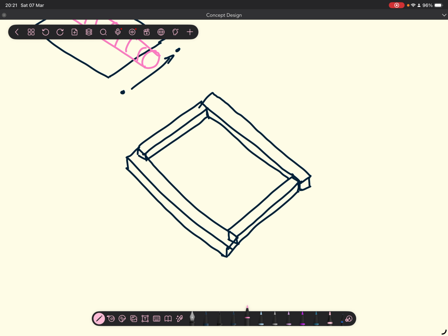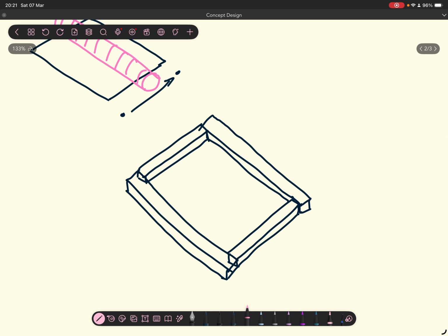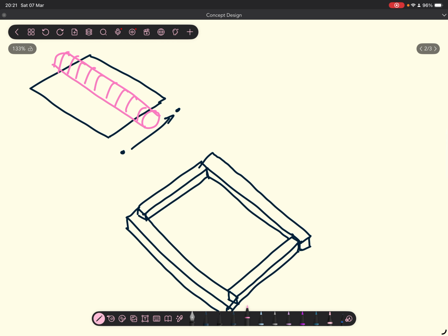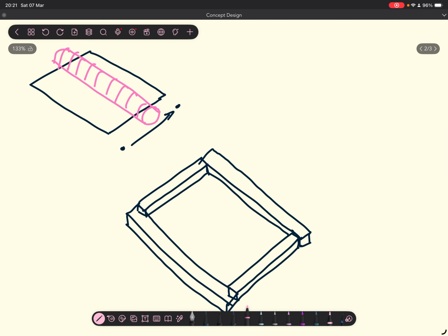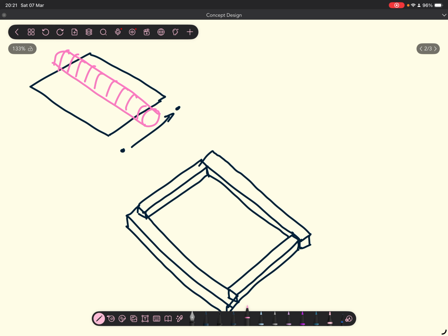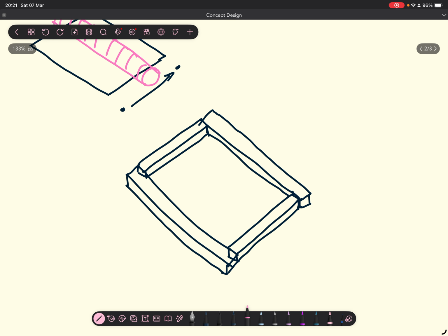You can look at Max Steel and see if you can find any steel sections to use in your design. Okay, but don't try and choose shapes now. Just get the general layout first, and then once you have your general layout, you can start doing basic load calculations and then choosing shapes from there.